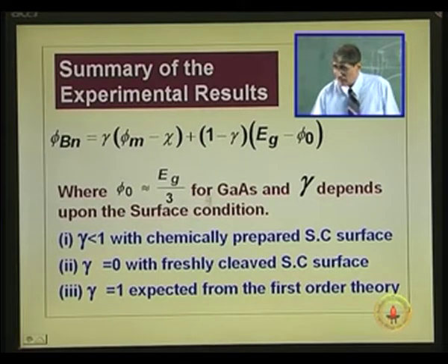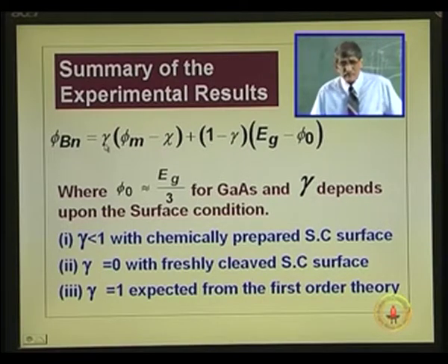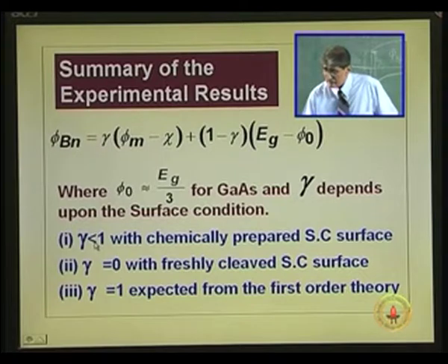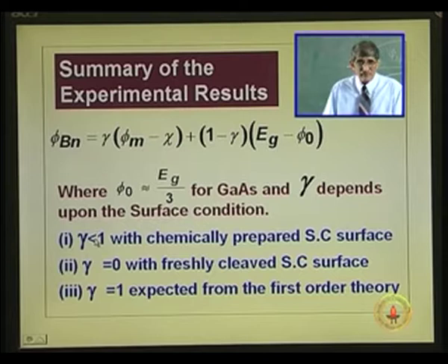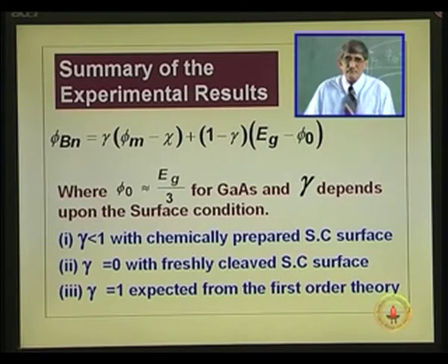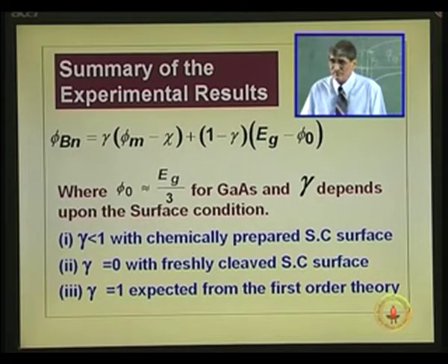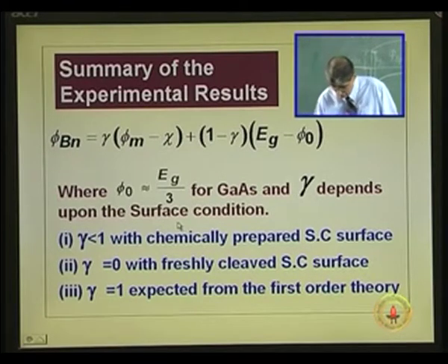Okay. Now, let us see what is the cause of this. Apparently or evidently, gamma is related to the interface state density DIT and some other terms. Gamma is between 0 and 1, it can be only between 0 and 1. Ideal 1 and worst 0. So, how that comes up, we will just see now.